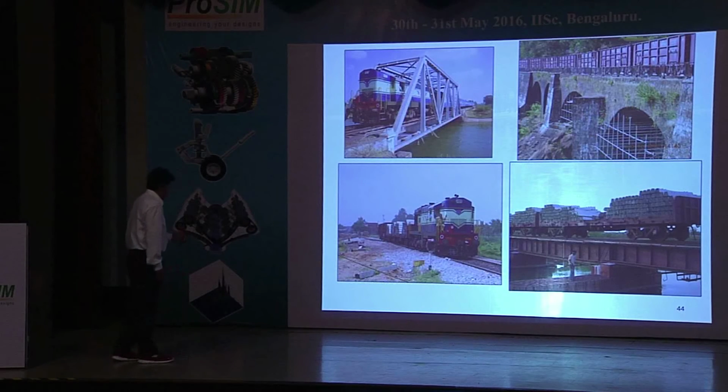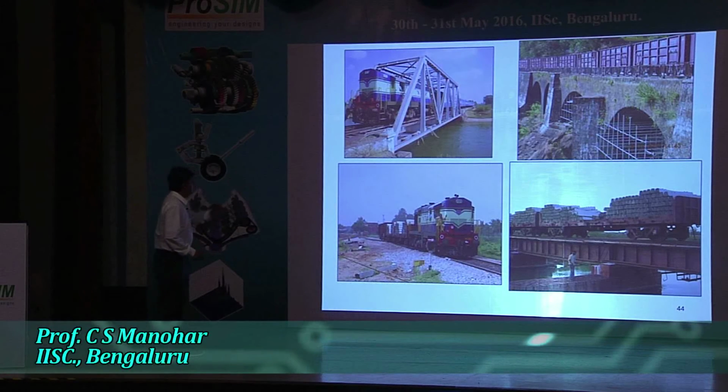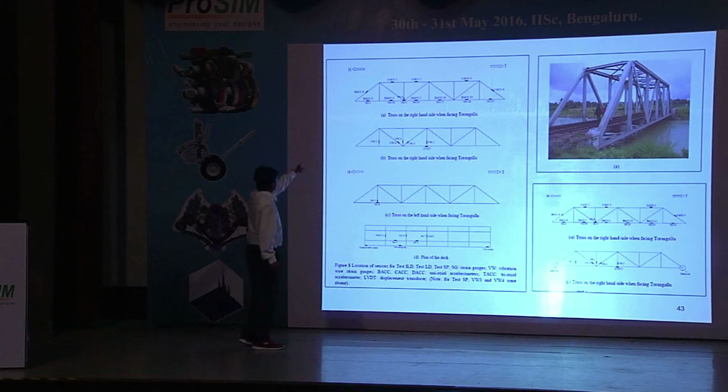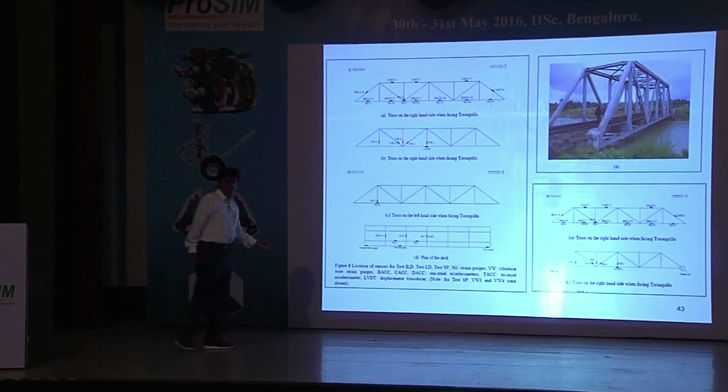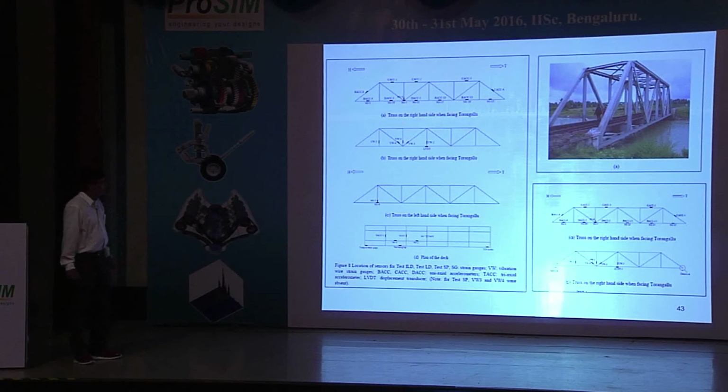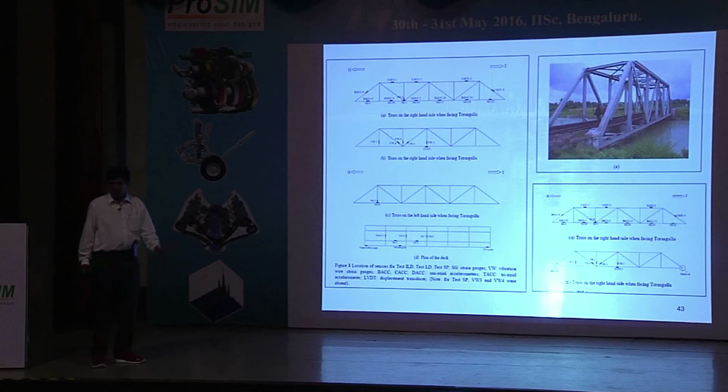Yeah, so these are the suite of bridges that we studied. Can you go back to the previous slide? It shows the sensor layout on that bridge. So there are accelerometers, strain gauges, tilt meters, and temperature gauges. We had a 96 channel data acquisition system, and the deal was that on every bridge site we would collect data for 100 hours. During that 100-hour window, whatever ambient traffic passes, we'll have records of all that, right?